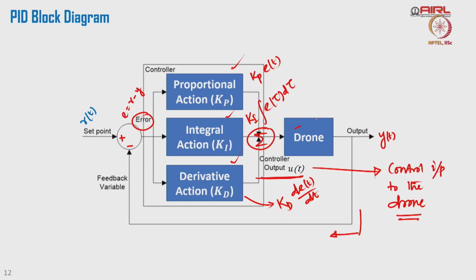So, the drone will have its actuators, those are essentially the motors for the propellers. This control input, which is prescribed by the PID controller, will then be effectively applied by the actuators. So, the thrust will increase in different propellers. Sometimes a yawing motion is required to follow the trajectory properly, sometimes pitching motions will be required.